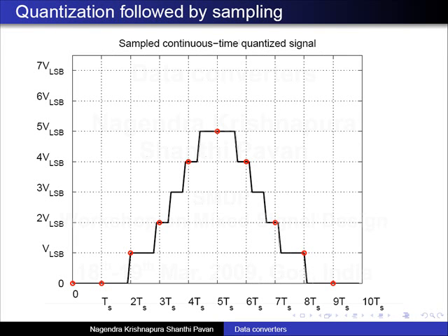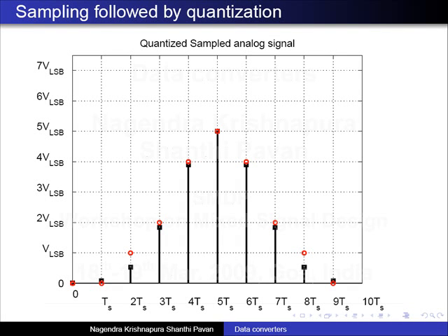So, we will come back to the statistics soon. Now, here what I did was I first sampled and then I quantized. In case of sampling, I had these Fourier transforms and I was able to tell you what the Fourier transform of the sampled signal looks like. It is simply copies. What will be the Fourier transform of the quantized signal?